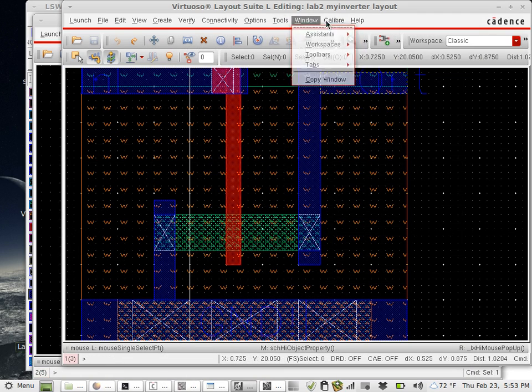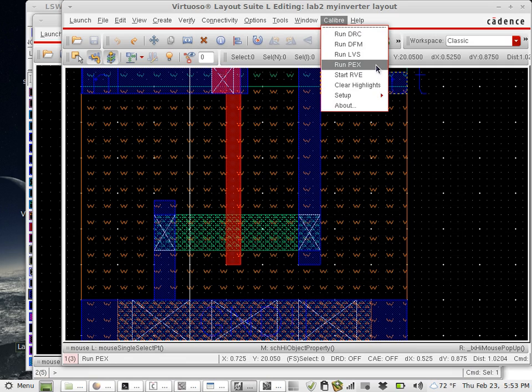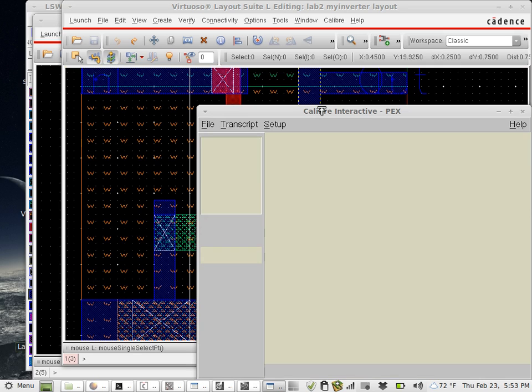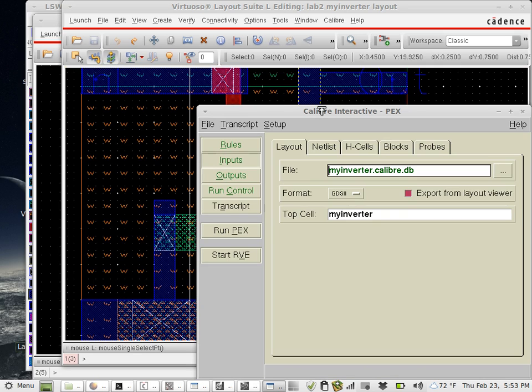which I get from running this. It's parasitic extraction, PEX. I'm not gonna go over that, but the result of this will be a spice file including the parasitics, much the same way that you have in Magic. And then you simulate that in HSpice on the command line.